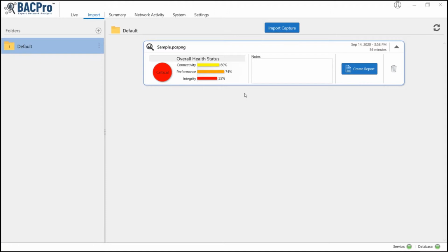The faster the reply, the better the score. Integrity is the score that starts at 100 and then is reduced for problems found on the network like duplicate networks, duplicate BBMDs, excessive traffic, and many other issues.